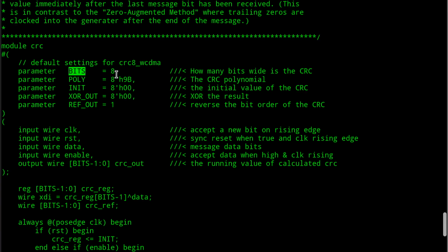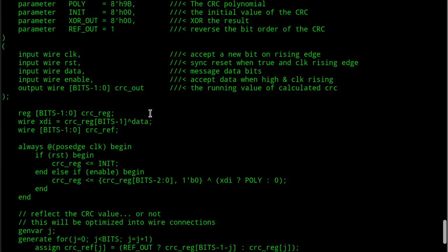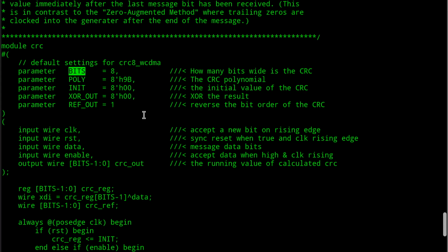Now, it's not to say it won't give you the wrong CRC if you have other bits wrong that are corrupted as well. But you can guarantee that if you have a group of bits that are corrupted and they're all close enough together so that the distance between them is less than this value, then it will generate a value that doesn't match the reference value that the transmitter, the originator of a message, would have calculated themselves. Okay, so that's how you detect. That's how you decide how many bits you're supposed to have.